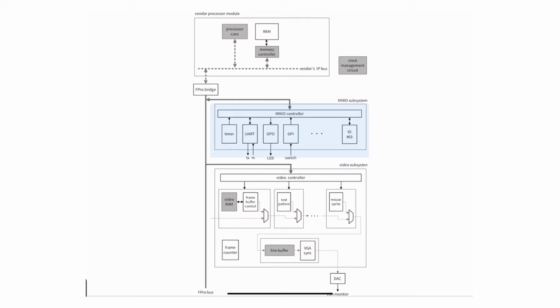You can actually just eliminate these GPIOs and put maybe 60 pulse width modulation, because your project has a lot of motors, or you just need it for some reason or another. It's up to you. That's the beauty of using an SoC on an FPGA, because you have the control over these. But what we're going to be doing is I'm not going to instantiate 60 pulse width modulation. I'm just going to show you a bunch of different IPs or peripherals, and we're going to place them in different locations in here, and how this works.